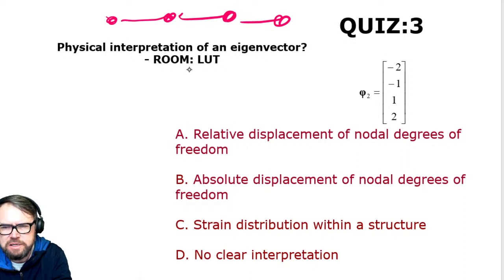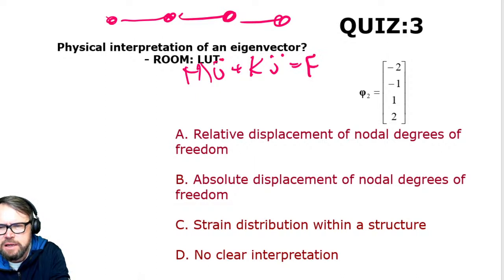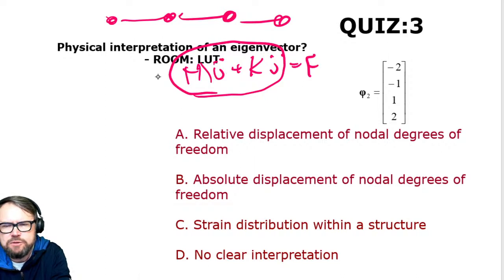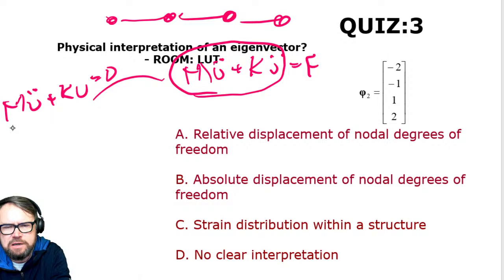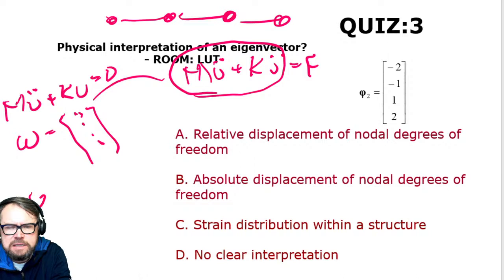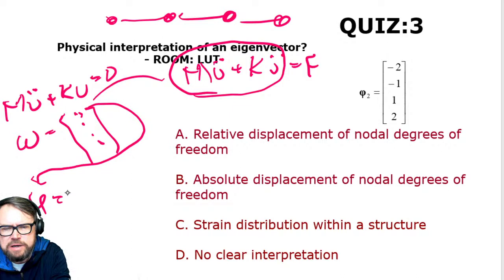So, a little bit unclear writing, but this is my equation of motion. And what I'm doing in my equation of motion is that first I'm going to take a look at these structural features. And when I look at these structural features, I can conduct an eigenvalue analysis. There are going to be an equal number of eigenvalues as the number of degrees of freedom, which are like these resonance frequencies. And each one of these eigenvalues will have an eigenvector. An eigenvector tells me how the nodes are moving with respect to each other in that particular resonance frequency.